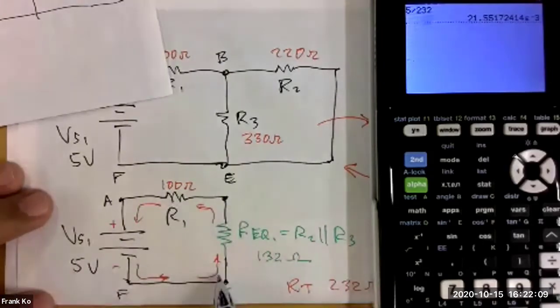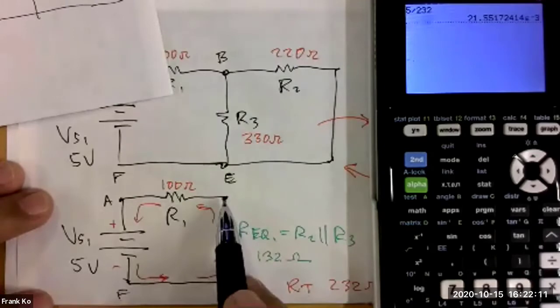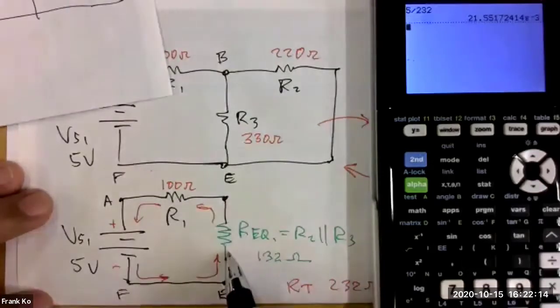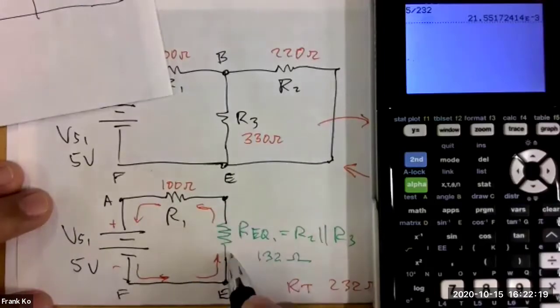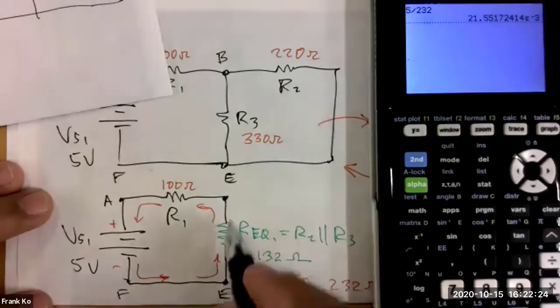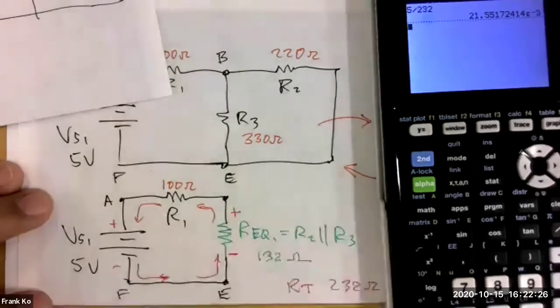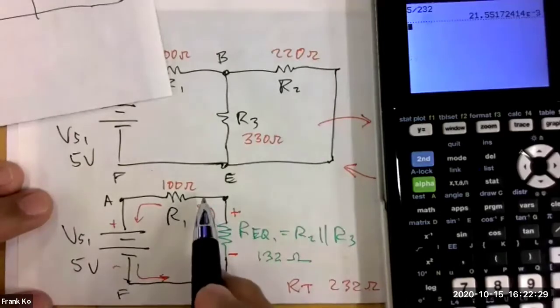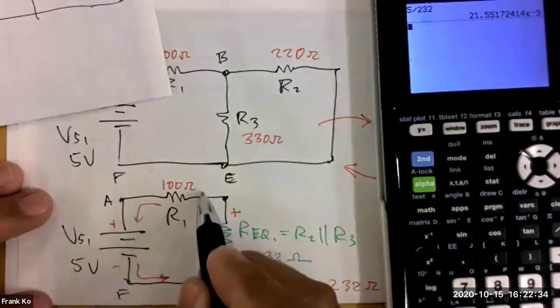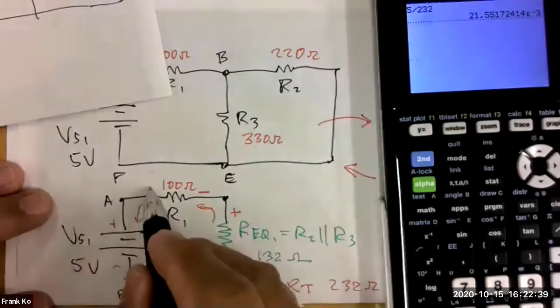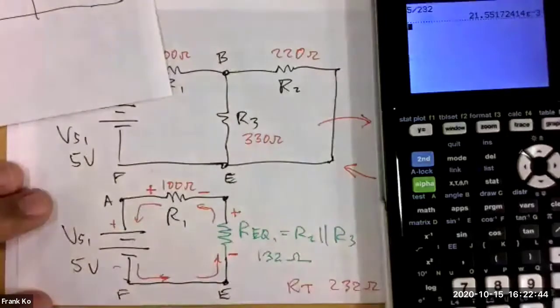Now, electrons, when they flow through a component, they flow from what polarity to what polarity? If you recall in your notes, electrons always flow from the negative side of a device through it to the positive side of that device. So as the electrons are flowing from the right side to the left, it always flows into what polarity on this side of R1? Always flows into negative and comes out on positive side of that device. That's the nature of electron current flow.